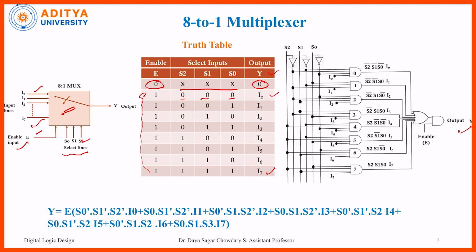So Y is equal to, this is again entirely a decoder circuit, and each time the decoder circuit gives each and every AND gate output, the product of S0, S1, S2. Here the first one is S0 bar, S1 bar, S2 bar, because it is given after the inverter circuits, and which is multiplied with I0, because my input here is I0. Likewise the terms are there, and finally all the 8 terms are given to one OR gate, and finally we get the output, that is Y.